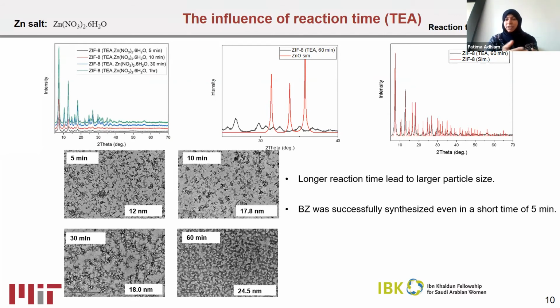So I was wondering if zinc oxide is present within the framework of the material or not. And as you can see here, when I try to match the peaks from zinc oxide, it is not matching at all with the reflections from the resulting material, which indicates the absence of this impurity.